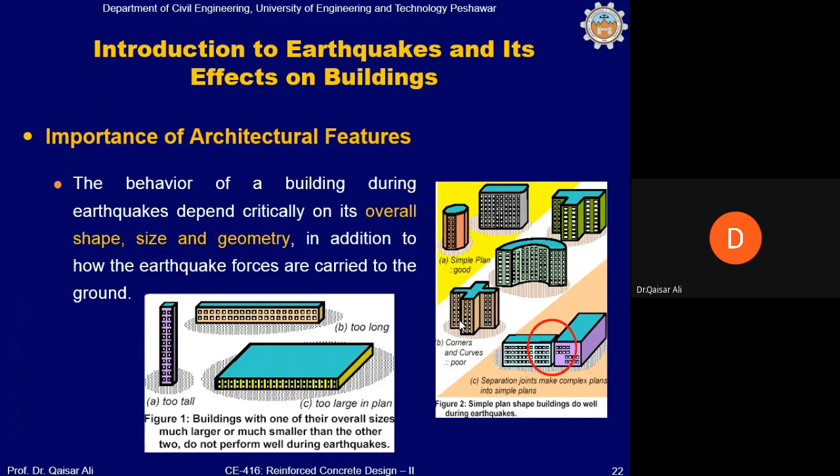and to increase the capacity of the structure against the torsion stresses becomes very costly. So when the structure from the beginning is planned in such a manner that the shape is circular or square or rectangle, then they are good shapes. These good shapes, simple plane with good shapes, will offer good resistance to earthquake, and then the structures would be designed as economical structures.